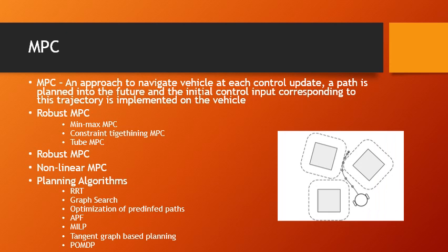Here we can see a summary of traits characterizing methods as we have discussed in the reference. Model predictive control is an obstacle avoidance trajectory planned offline. There is a lack of flexibility when subjected to a bounded disturbance. MPC combines path planning with online stability and convergence guarantees, as it is done by performing the path planning process at every time instant and applying the initial control related to the chosen trajectory.